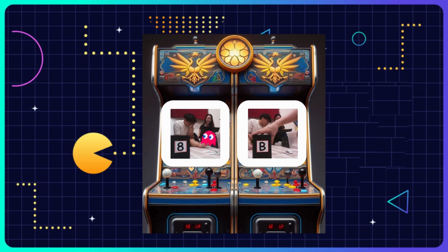So, for image recognition, we have to detect the symbol from an image. The task sounds simple, but there is a pitfall that many will fall into. Take a look at the two examples taken from the RPi camera, B and 8. As you can see, they are actually very similar to one another, and this is a huge issue. Most teams will use an object detection model and realize that their model has many false positives, resulting in high classification loss. This is due to the fact that there are 31 symbols to classify, and each symbol has the same color, size, and similar shapes.